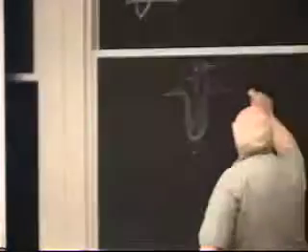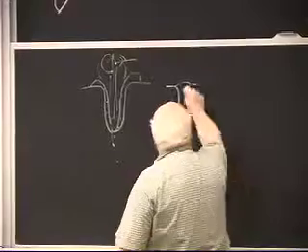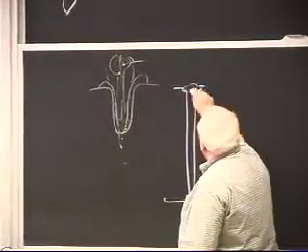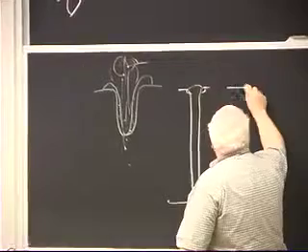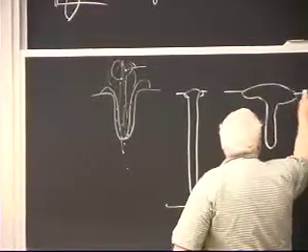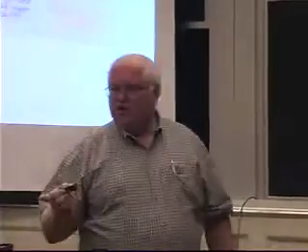Now, what happens because of that, in electron beam, if you look at a deep penetration electron beam weld when it's all done, you could get something that looks like this. And you might get a little of what we call a nail head up here. But in laser, you'll get big nail heads. You get something that looks like that. And I actually have here a laser-assisted arc weld.